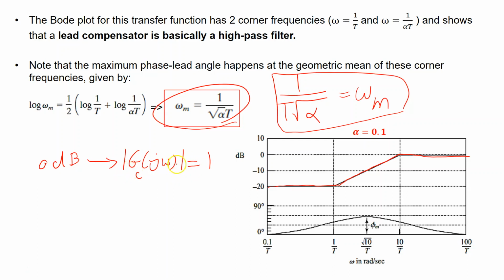If you send into this compensator a harmonic of magnitude 10 units, it gives you back output of 10 units. It's not going to bring the magnitude down if the input that you passed in has a high frequency. Okay? On the other hand, if you pass to it an input with a low frequency, what happens?